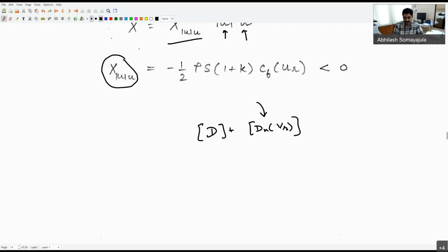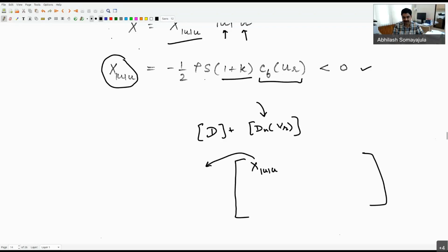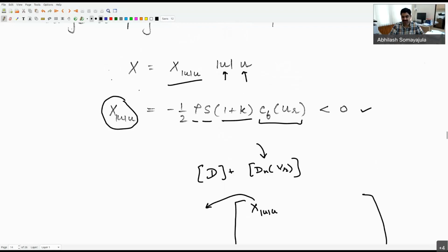So if I wanted to include that here, then the first term of that matrix would be something like maybe C. And that value is given by this expression, given that I know what the skin friction coefficient is, what the form factor is, what the surface area is, and the density of the water. If I know these things, I can approximately compute what this coefficient of quadratic damping in surge will look like. Everybody with me so far? Yes? All right.